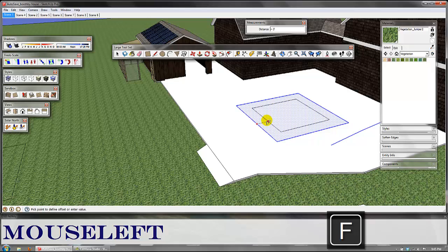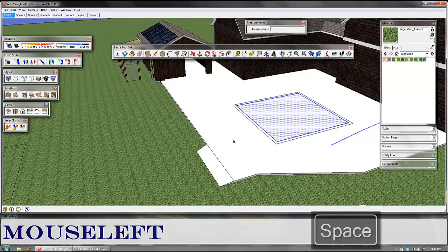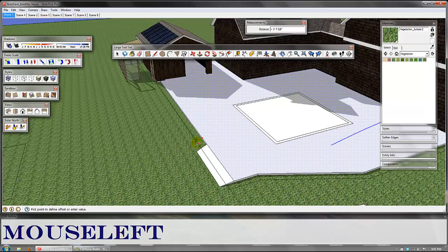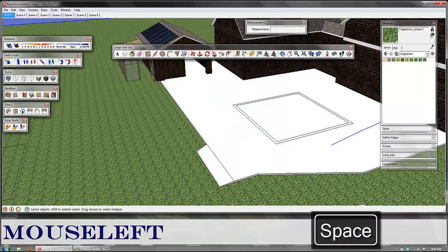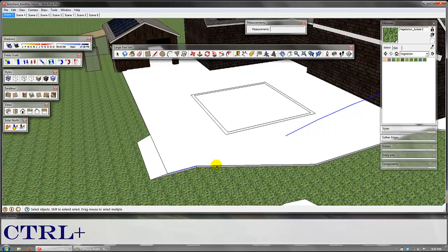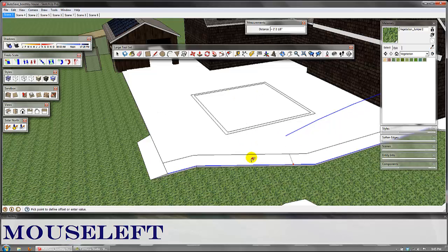And now you can see in my measurements box, I can create an even offset, 8 inches in either direction. And this works with whatever shape you have. It can be curved, whatever it is, it's going to follow the closed path of this shape. And you can also select 2 lines, or 3 lines. If I want to make an offset of just these 3 lines, I can do that with the offset tool by making the selection and then telling it what to do.